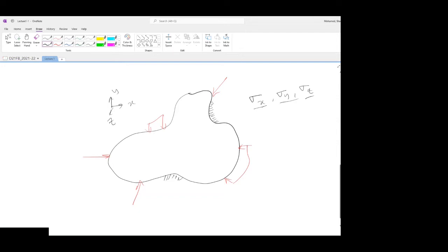And this is the real problem. This is the situation where you are going to need to figure out something to do with these values for the stress. It is actually the principal stresses, yes. So what you should be using is the principal stresses, not sigma x, not sigma y, not sigma z. It should be the projection on the principal directions.